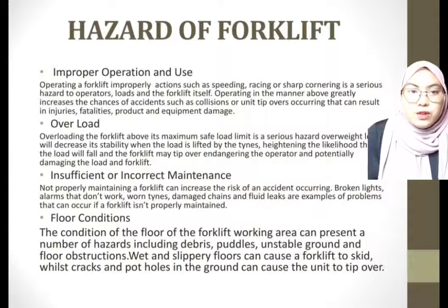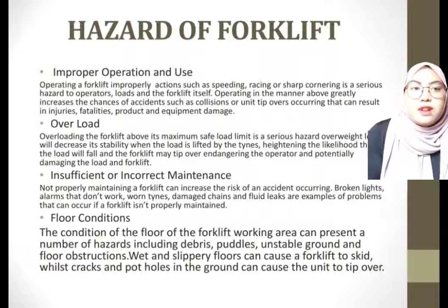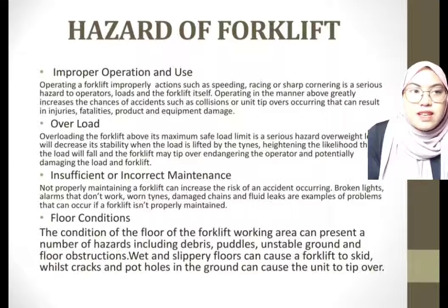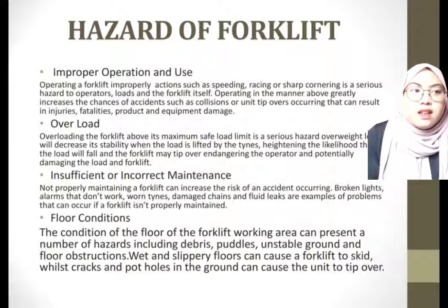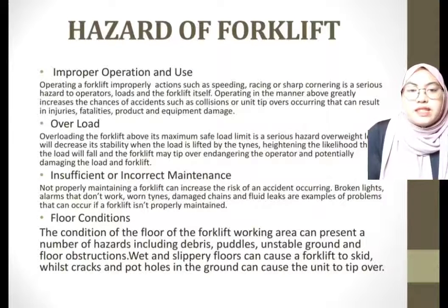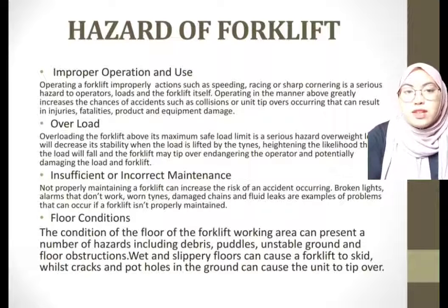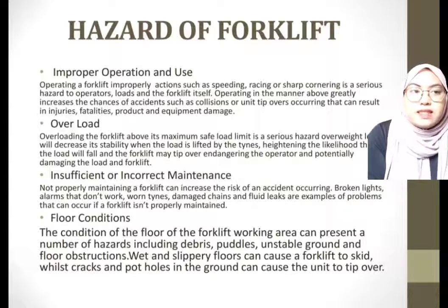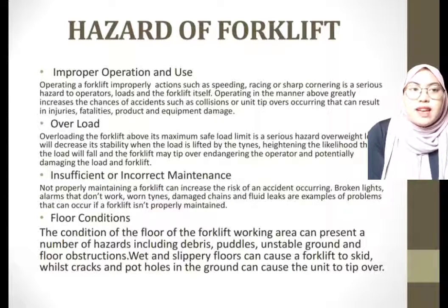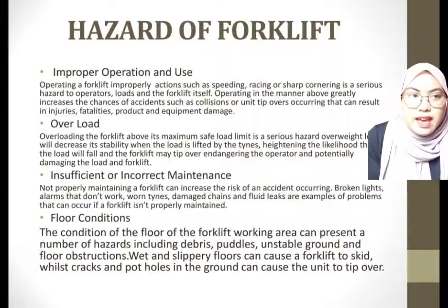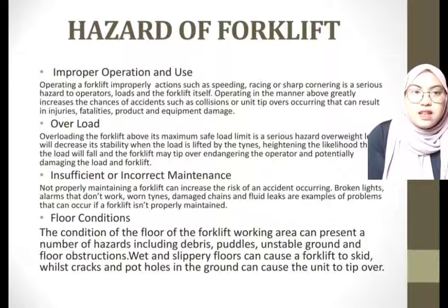Secondly is overload. Overloading the forklift above its maximum safe limit is a serious hazard. Overweight load will decrease its stability when the load is lifted by the tines, heightening the likelihood that the load will fall, or that the forklift may tip over, endangering the operator and potentially damaging the load and forklift.